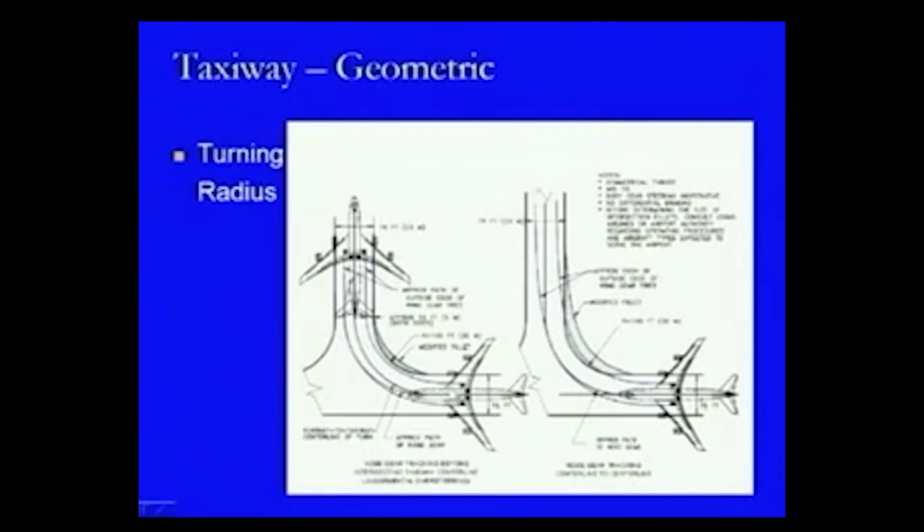What he is trying to do is that this particular gear, which is on the inner side of the curve, is moving like this, and during this movement it should remain clear of the edge of this connectivity. That is the basis of this particular judgmental oversteering method, or judgmental oversteering, adopted by the pilot.